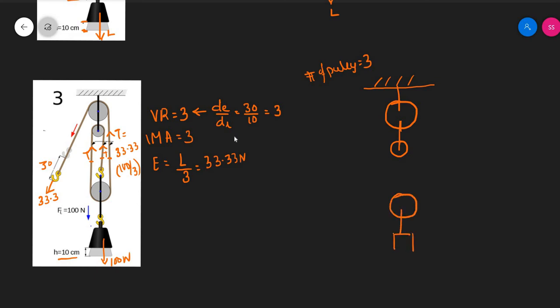And once you do this, then you always start drawing from the effort side, so you know how to loop your pulley up. So the rope, the tackle system goes like that, and it loops around, and you see here it hooks up in the bottom, unlike in the previous one where it was hooking up in the top.